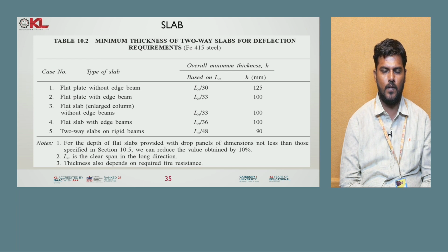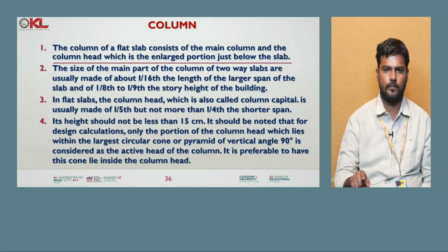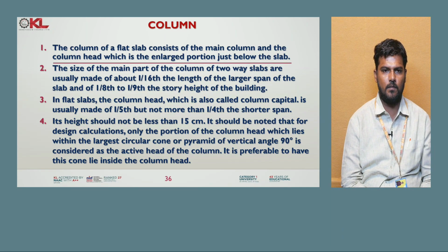For the depth of flat slabs provided with drop panels of dimensions not less than those specified in section 10.5, we can reduce the value obtained by 10%. Here ln is the clear span in the long direction, and thickness also depends on the required fire resistance. So you can see here what is meant by column.